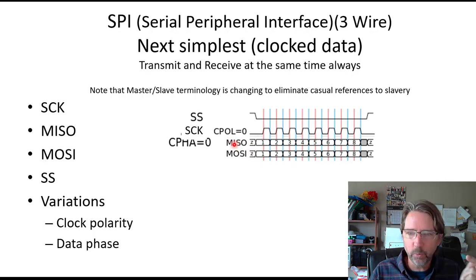So if you wire these together, MISO goes to MISO, and MOSI goes to MOSI, and S clock goes to S clock. So it's not like RX to TX in the other serial, the asynchronous serial. So you wire the same names together. And there are a lot of variations on this, whether you use the rising edge or the falling edge to send the data or set up the data or read the data. So it's not very standardized and you have to read the data sheet. So this is just one example.